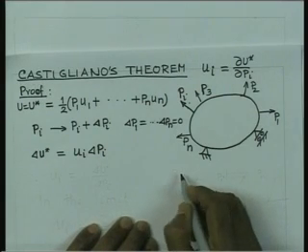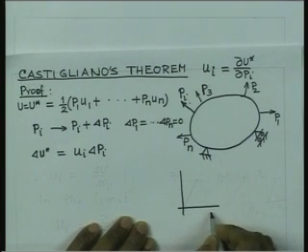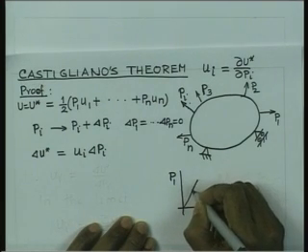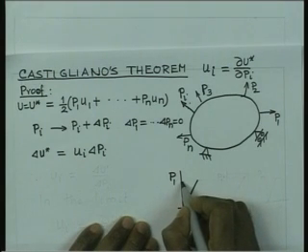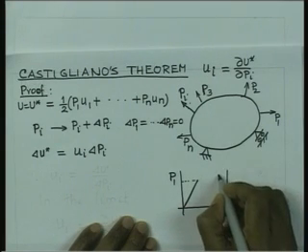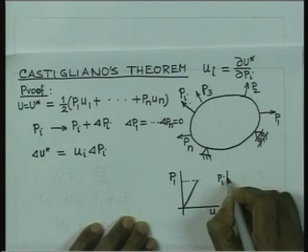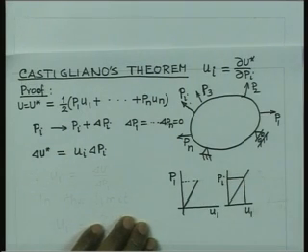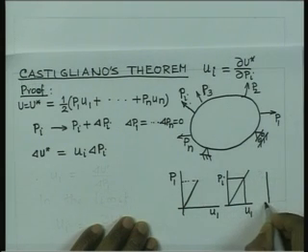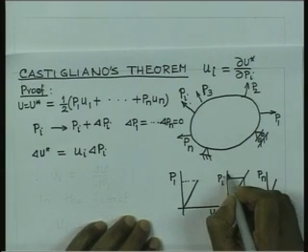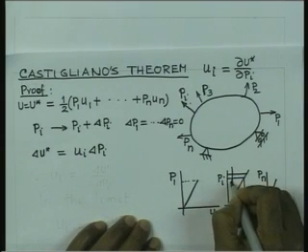Let us understand this. If we consider the deflection of each of the load points, like P1 U1, we would have got the deflection like this after it has reached the level P1. Similarly, if we consider the load Pi, after we have reached the level Pi, we would have got the deflection given by Ui, and this is the variation of the deflection. Similarly, we will have Pn varying with displacement like this, and now what we are trying to do is increase the load Pi by a small amount delta Pi.